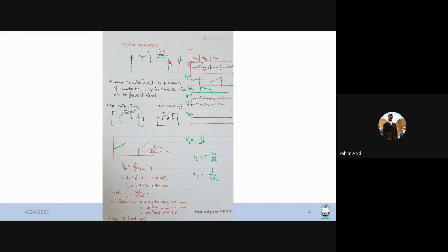As well, this capacitor is also not ideal. There are some resistances also in the capacitor, which will act as a loss component, as well as the switching losses and the conduction losses in the transistor, which will contribute to the power losses. So your output power, in the actual circuit operation, will not be ideal. That means the efficiency will not be 100%.